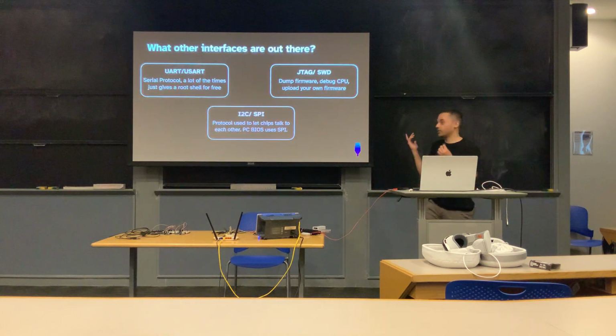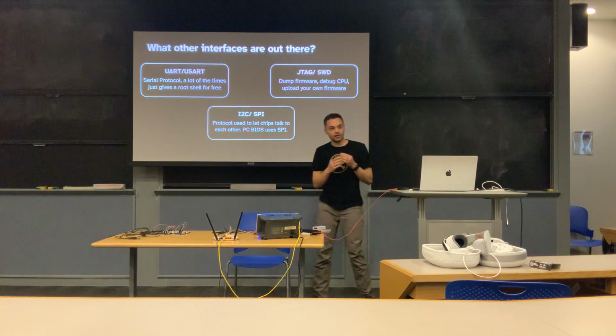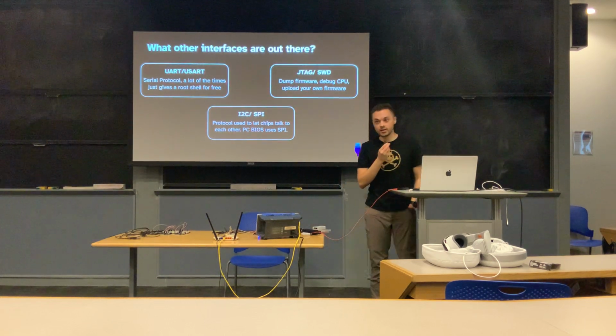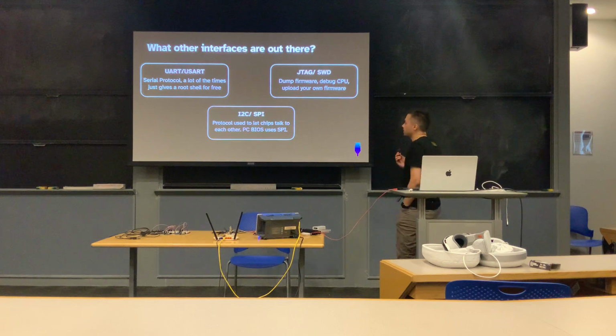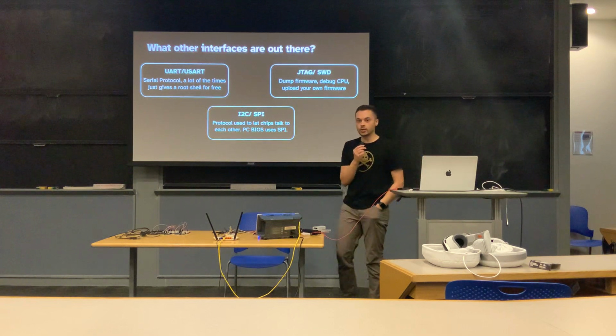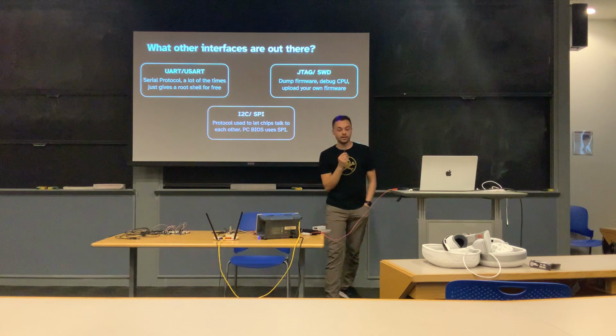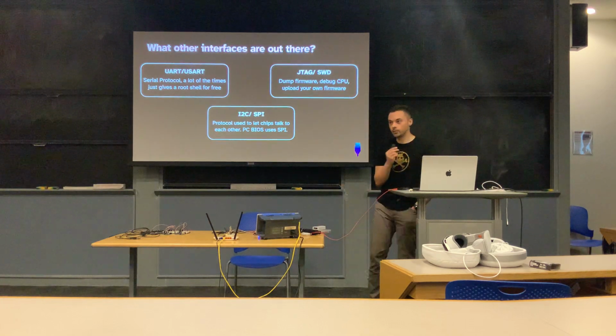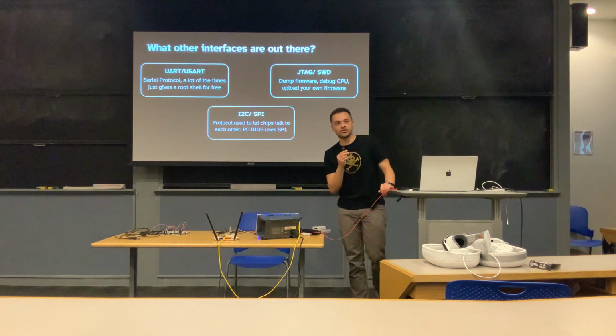So what other interfaces are out there? So you asked earlier, what else can we find? So UART's a very standard one. It's a serial protocol. You'll find it on most devices. There's also I2C or SPI. So earlier we saw that SPI chip for that non-volatile flash. When your PC BIOS starts up, it actually uses SPI. And so one thing, if you want to see more, you can come to Office Hours and we'll show you.